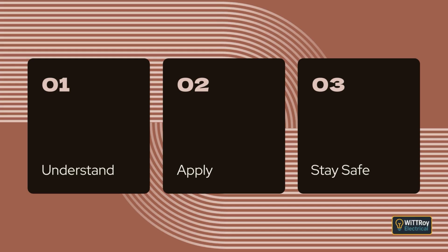Any screw that touches a conductor must be designed so it does not cut into the conductor strands. These terminals are often used for important conductors such as the incoming neutral, the main earthing conductor, the MEN link, or APEN conductor. Because these are critical conductors, the terminal must either use two screws or use one screw with a large enough diameter so the conductor is not damaged.